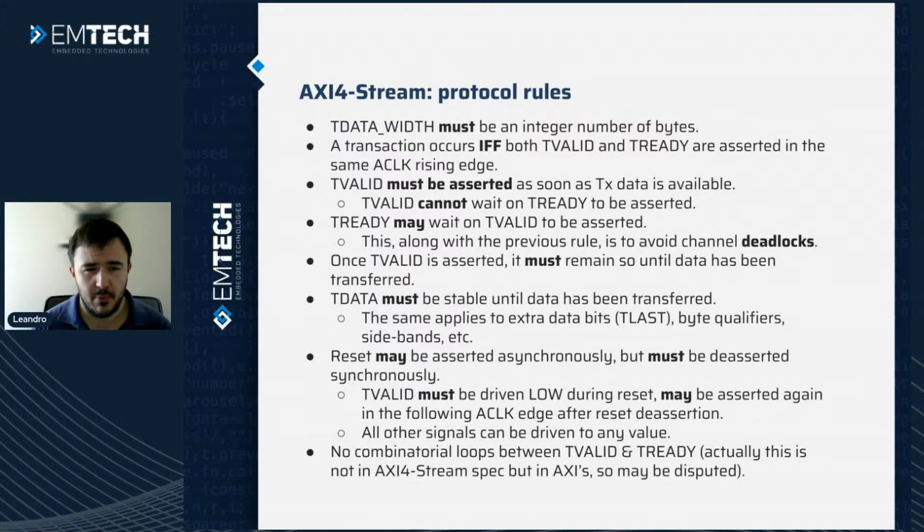There's another rule that people talk about a lot, which is that there shouldn't be a combinatorial loop between TVALID and TREADY. But during my research for this presentation, I found out that this doesn't appear in the AXI4-Stream spec, but actually it's part of the AXI specification.